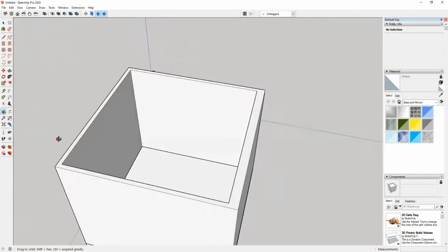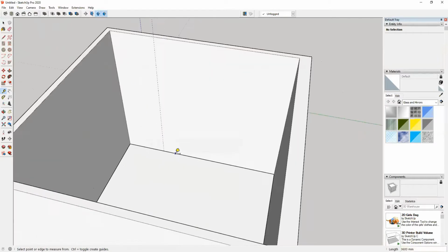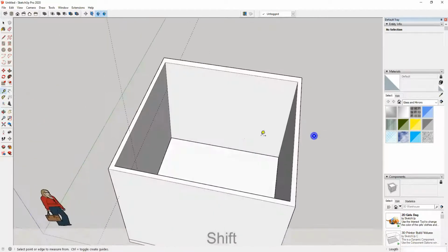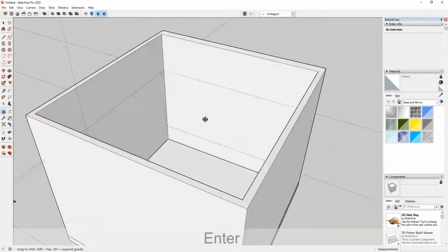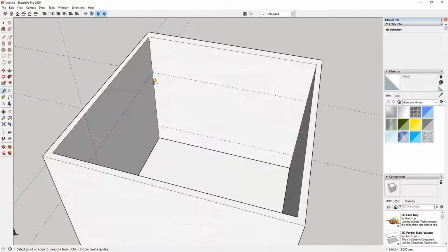Now let's use the guides to create our door first. Let's have a door of 900, enter, and the height of the door will be 2100. I'm just considering standard ones. Now here I will need a window at a height of 2100, say, with a sill level at let's say 450. Okay, so we have the sill level and the window. Now from here I'm considering 750, and from here I'm considering 750 for our window.